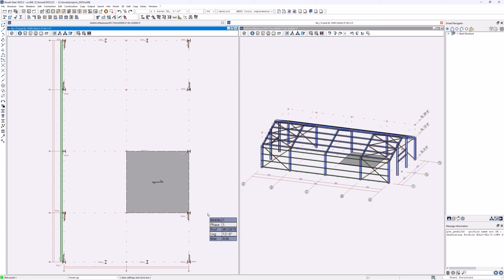Also, there will be a little symbol to show that it's not just a regular plate, because the properties are a bit different. A regular plate can be mirrored and they will still be identical, or could very well still be identical, but when you mirror a grating, it becomes a mirror image of the original one and will have different mark numbers. So there's different properties between a regular plate and an actual grating. And now we know this, we can start fitting in some connections.